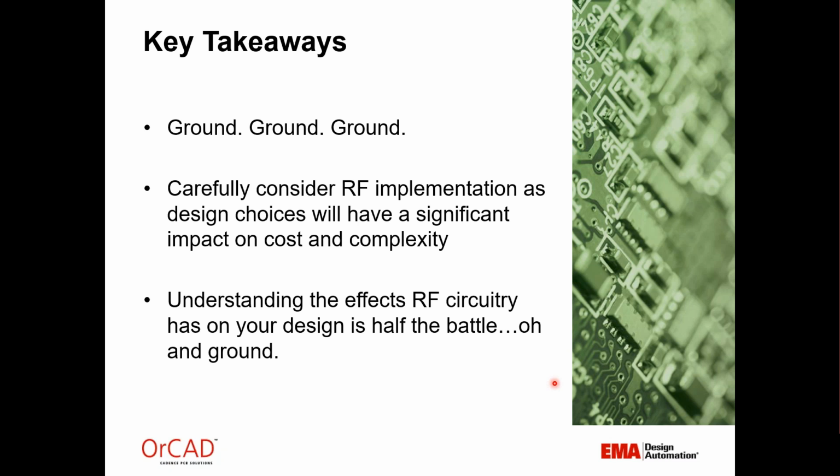Carefully consider RF implementation as design choices. It has a significant impact on the cost and the complexity of your designs. Understanding the effects RF circuitry has on the rest of your design is half the battle. The real issue will start when you have an RF circuit that needs to be added to a digital design that's already complete. They do not get along. So grounding is your best defense against that battle, and then simulation of the entire board.